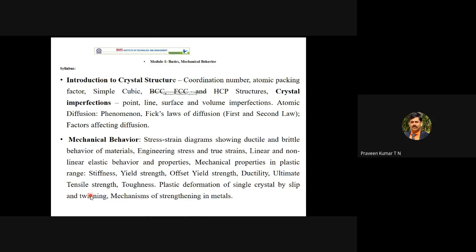At the macroscopic level, you see some deformation when the material is pulled, maybe 1 mm or 2 mm. But at the crystallographic level, how does deformation take place? We have a group of BCC cells, which is nothing but a crystal. FCC, for example, is aluminum. We can analyze smaller and smaller substructures very easily.